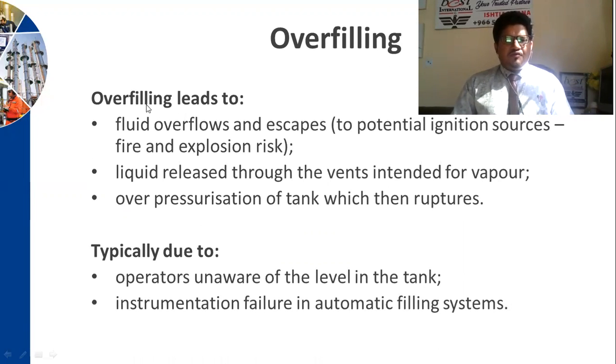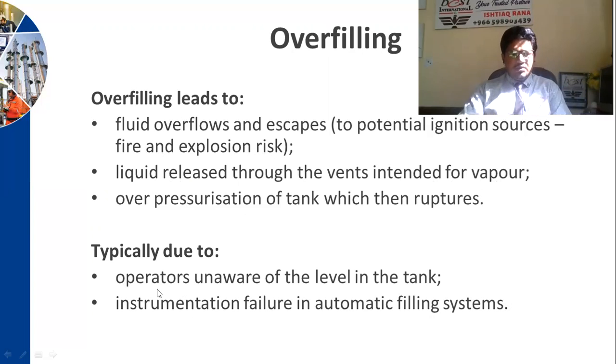Overfilling leads to fluid overflows and escape to potential ignition sources, with firing and exploding risk. Overfilling is a terrible hazard also. Liquid is released through the vents intended for vapor. But if these vents are blocked, not working well or not designed well, then it would be horrible. Overpressure of the tank then ruptures it, typically due to operators being unaware of the level of the tank or instrumentation failure in the automatic filling process.